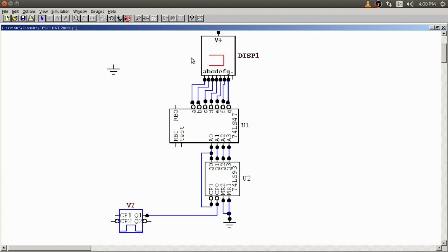So after some familiarization, just by looking at those characters, we know what the code is. For example, small c is 1010. The opposite of c is 1011, and so on. Because in a digital display you need to display only 0 to 9, you do not have to go beyond 9. So we really don't bother about what display is coming. But anyway, this is a good exercise to remember what it's showing, because then we can identify what the input to this will be.